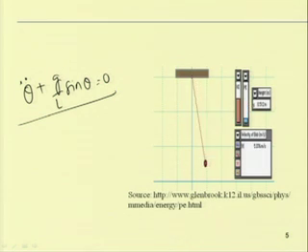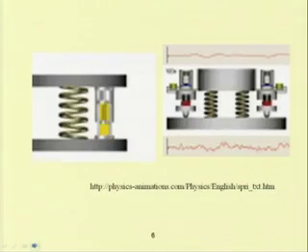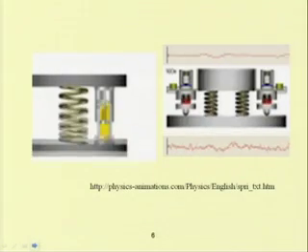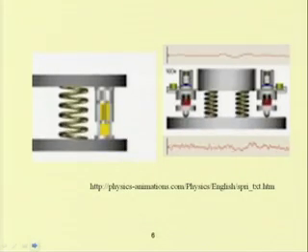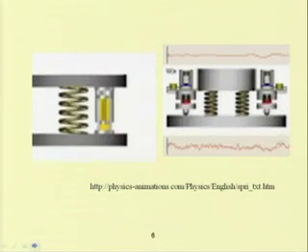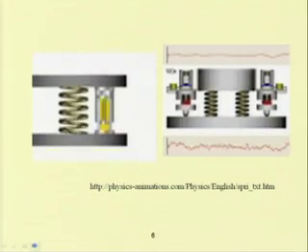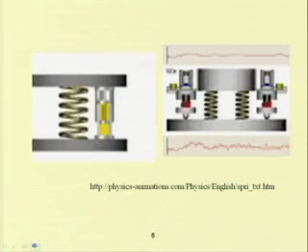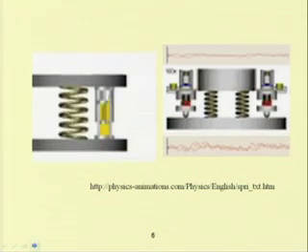But if theta is not small, then one has to expand the term sin theta up to its third order, fifth order or higher order and write the governing equation of motion. Similarly, consider a simple spring mass damper system. The spring may be linear or nonlinear. Depending on hardening or softening type of springs, one can write different equations of motion.